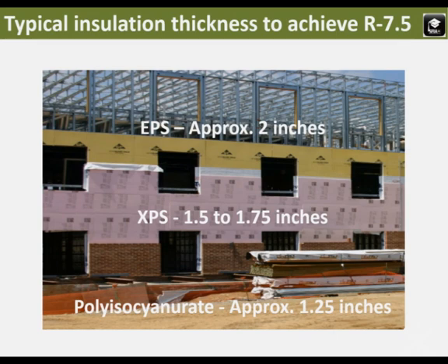So what does this mean in terms of insulation thickness? It depends on the specific product density and the manufacturer. Unfortunately, thinner products are generally more expensive. Polystyrene foam boards, usually EPS or XPS, will be between 1.5 to 2 inches. This makes for some very long fasteners for the foam and siding attachment.